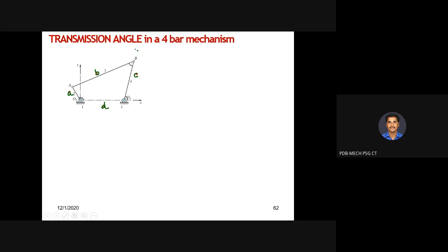Look at the diagram and tell me what is the variable which is required to locate the orientation of each and every point of the mechanism. Any idea? Either you can change the dimensions of the links to have different orientations, or we need to have theta.